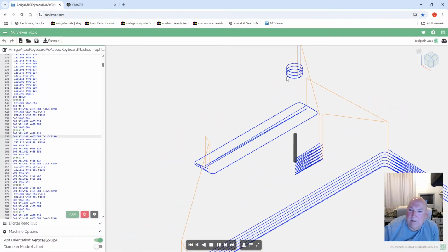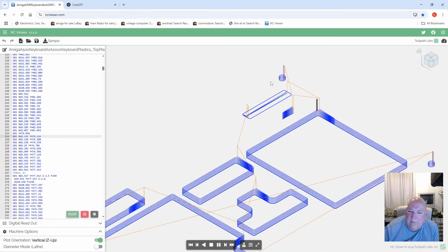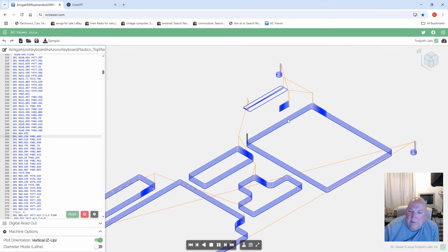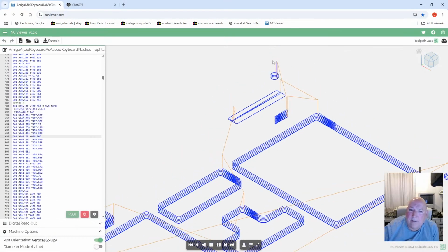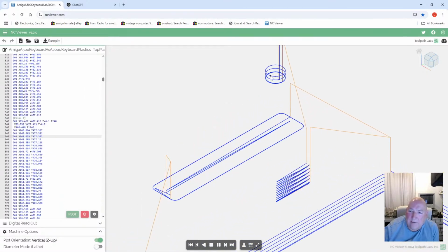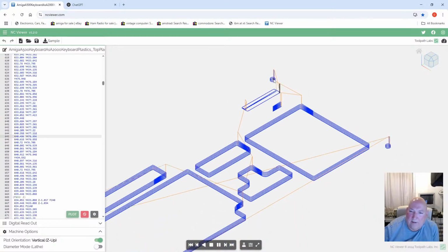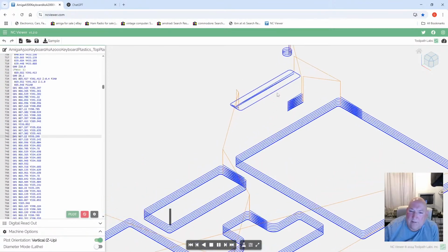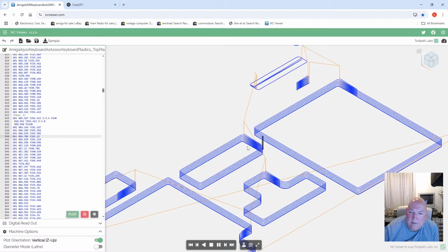cutting out the pockets. You can count them, so depending on how many the multipass depth is, that's a complete cut. So you've got 1, 2, 3, 4, 5, 6, 7, and here you should only have about 3. 1, 2, 3 and a bit, yeah. So that shows you it's only going to mill halfway through. This is just going to go. That's an inside cut.